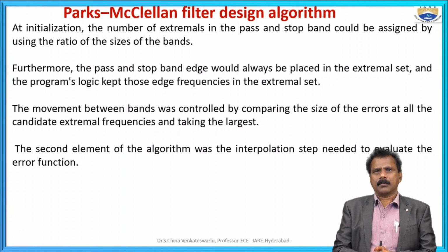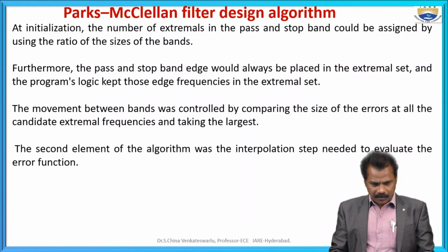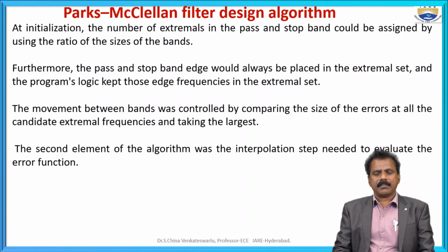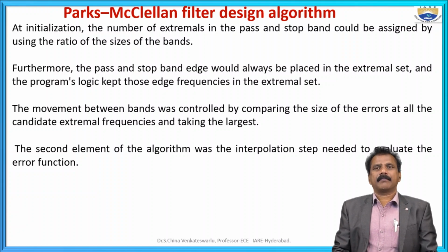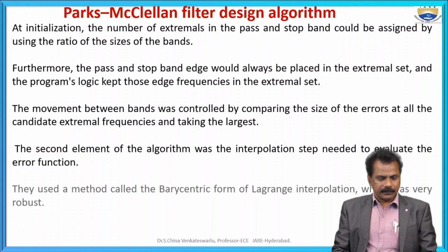Here you are right to observe that we are comparing the size of the errors at all the extremal frequencies and taking the largest. The second element of the algorithm was the interpolation step needed to evaluate the error function. They used a method called the barycentric form of Lagrange interpolation, which was very robust.